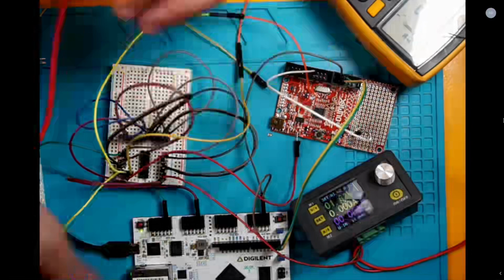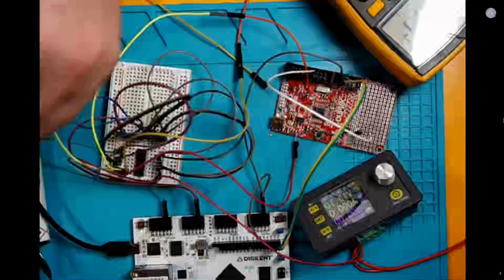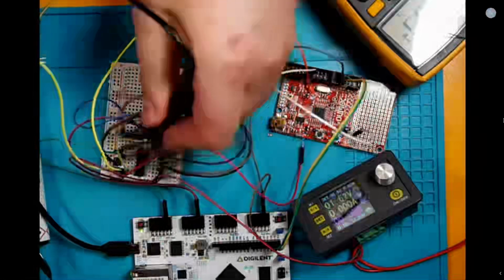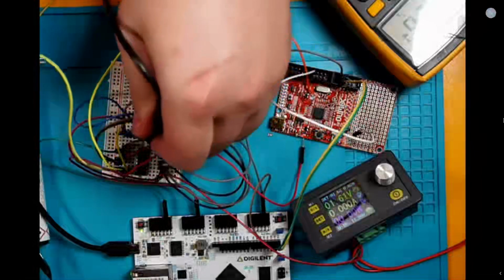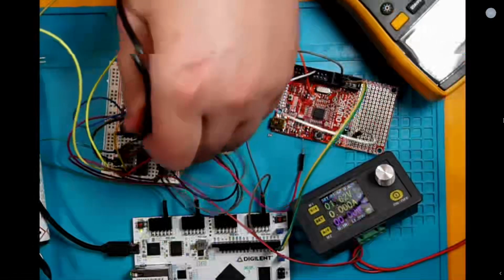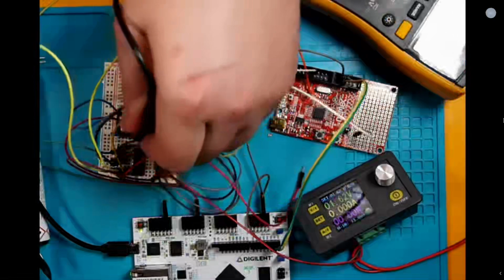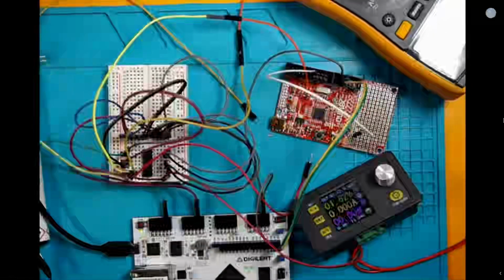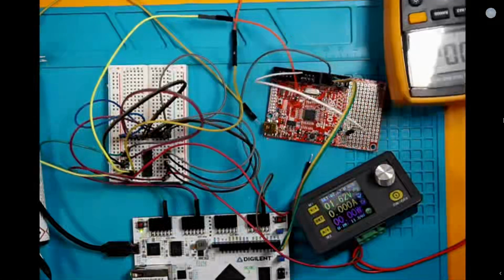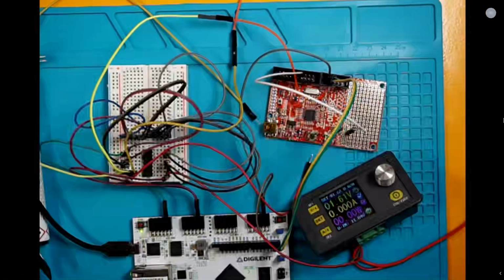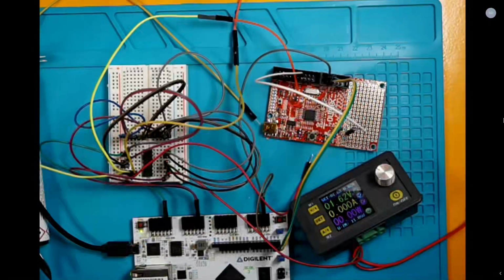So for that, I have this guy right here. Let's connect it over here. And let's connect this one over here. So it's slightly off the screen. Unfortunately, with my lamp, it's coming off. So you'll have to take my word for it. But we're getting the 1.62 volts on the output. So we should be good to go. We also fortunately have an oscilloscope for this, and we can make sure that everything's working.